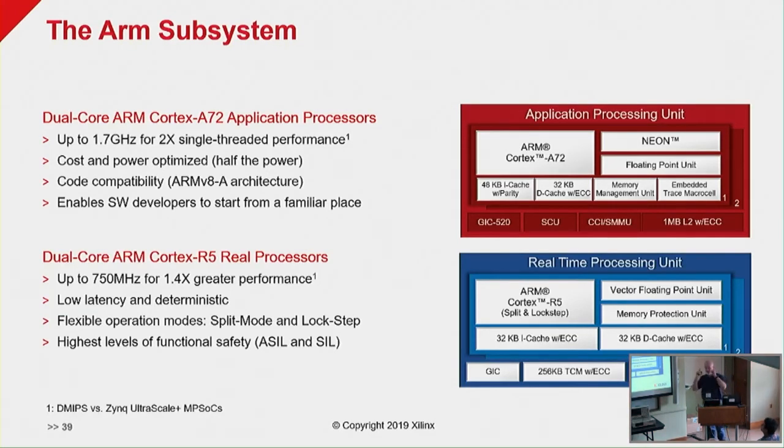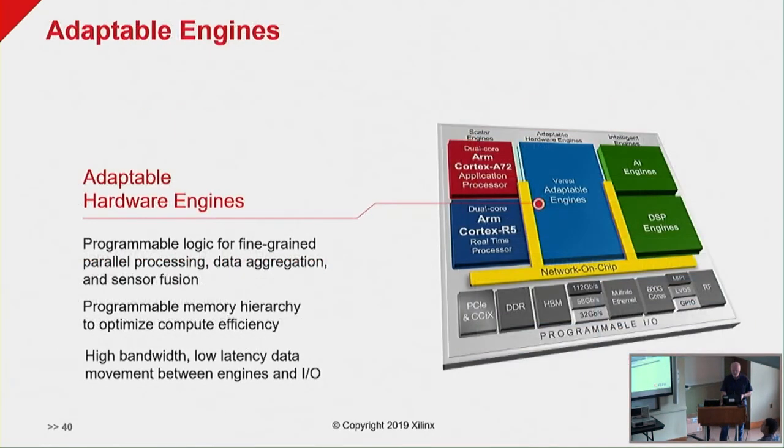You can have the two processors executing the same code so that if you get out of lockstep, you know you've got a problem, etc. So this is very targeted at security and that side of the house. This is the kind of thing that would do your Linux, your network interface for your low-speed interfacing, etc., and command and control, if you will.